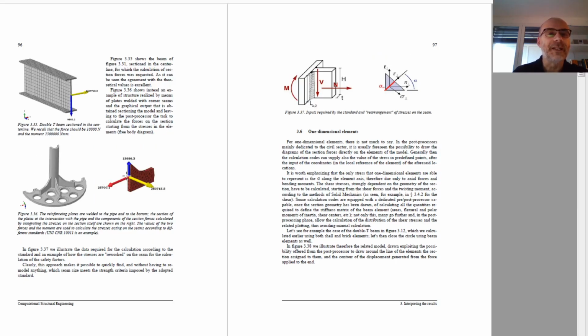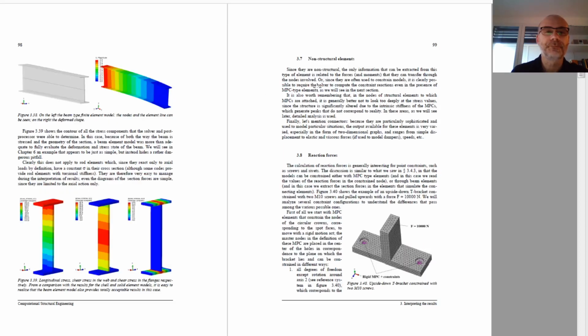And then for welded joints, so continuous joints, it is shown that some codes allow to extract the section force by simply cutting through a plane and then asking the code to integrate the stresses and then extracting the section forces to be used, like we see here, for some normatives to calculate seam corner welds, for example.